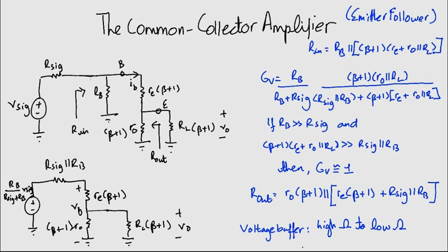The resistance reflection rule may sometimes seem like much of a hassle, but in reality, with practice, you can mentally do the calculations and reduce your time considerably. As a task, try the resistance reflection rule on the output side. That is, instead of multiplying beta plus 1 on the emitter resistances, multiply the input resistances with beta plus 1. This way, we will be reflecting resistances to the emitter side. You should have identical results for Rin, Gv and Rout.